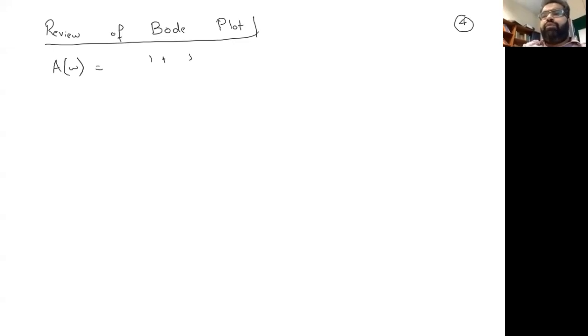And again, you have seen this, I assume, a lot of times, or that's a fundamental in your control course. So again, going back to the same dynamics, where we have a frequency dependent gain, which has some poles and some zero information. So for example, we have A over (1 plus j omega over omega Z) divided by (1 plus j omega over omega P1). So I'm just drawing 2 poles and 1 zero, just to clarify. But you can have any system. So it's not bounded by this one, but you can have any system.